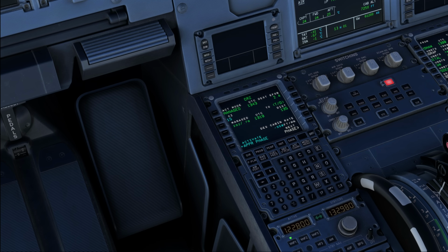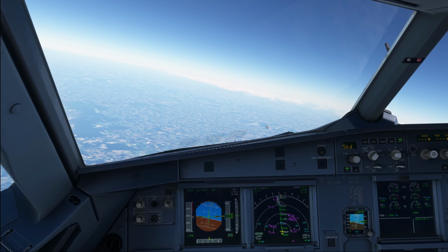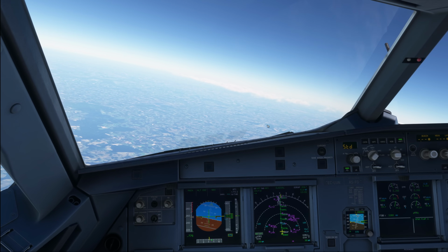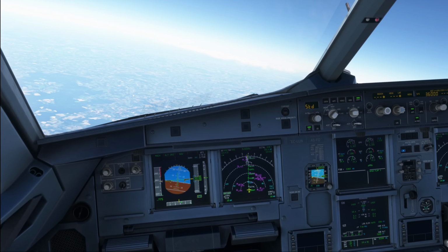You've got noise abatement procedure 1 and noise abatement procedure 2. Procedure number 1 includes the acceleration only at 3,000 feet above the ground. Obviously this means flying at slow speeds with the flaps extended for a longer time, and that is obviously going to increase the operating cost of your flight by increasing fuel consumption quite a bit.